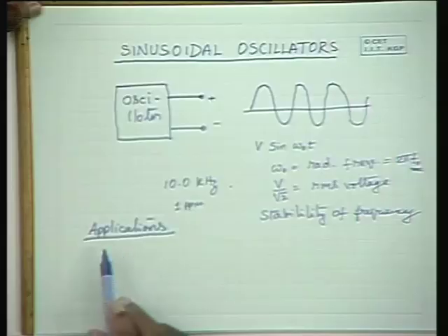So, the signal generator we use in the lab, does it work as an oscillator? So, here is a question. Yes, the signal generator you use in the laboratory is an oscillator. It gives you an oscillating voltage. It gives you a few functions like sine wave, square wave and triangular wave. Some of them give you sine wave and square wave, and the frequency is variable, amplitude is also variable. So, that is a function generator and it uses an oscillator inside.